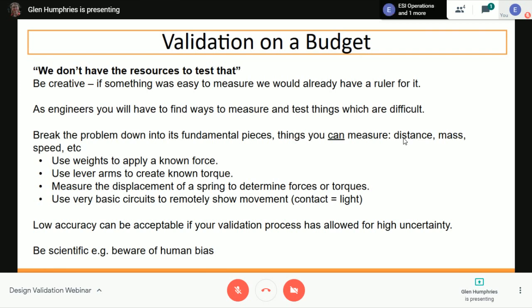And there's so much you can do with just simple things, particularly just trying to focus on one validation aspect at a time. A lot of your components are quite complicated. For example, a suspension upright does a lot of jobs at once. It's very tricky. Focus on just validating one thing at a time. Caveat there, you do have to consider combined loads, but you can validate some reasonably fundamental things about your design by just focusing on one thing at a time.